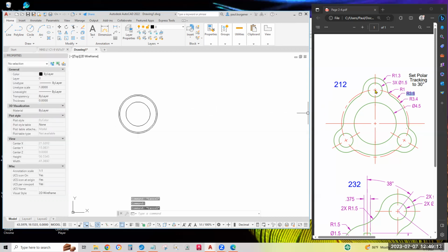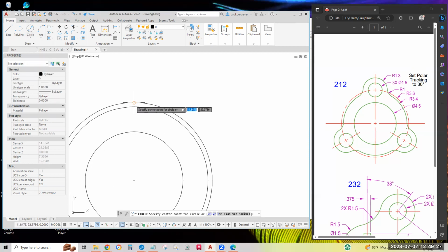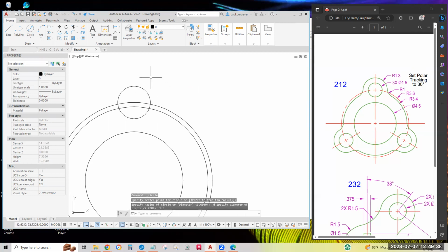Okay, top dead center of the outer red circle, I want to put a circle whose diameter is 1.5. We'll click circle center diameter. Snap at the top dead center quadrant of that guide circle, and the diameter is 1.5. While we're here, let's draw a circle for the green arc that we'll use the trim command later to switch from a circle to an arc.